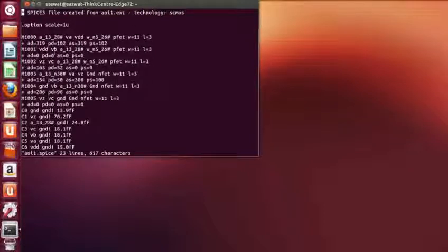This is the area of diffusion, this is the perimeter of diffusion. This is the same for the substrate. This is MOSFET 1, this is VDD, then VB, and similarly over here for the others.